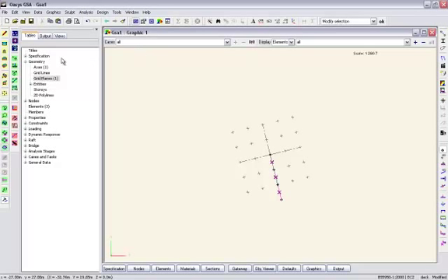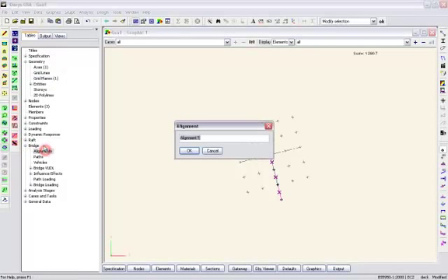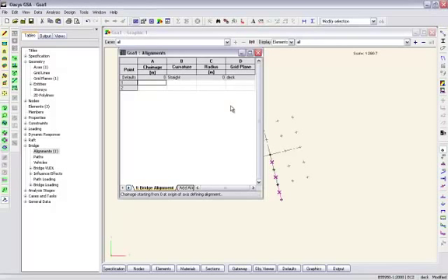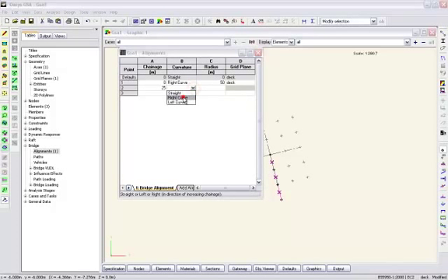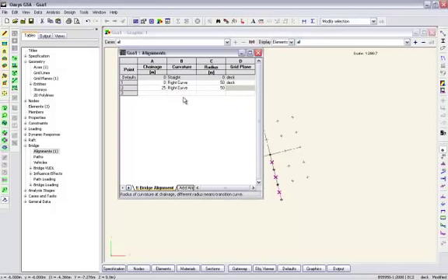Now to define the bridge, I also mentioned we need to create an alignment. So let's get on the bridge section, and call it bridge alignment, something original. And the details of this, I'm going to start off at 0 with a right hand curve, radius 50 meters on the deck plane, and then at 25 meters is also a right curve, 50 meter radius.